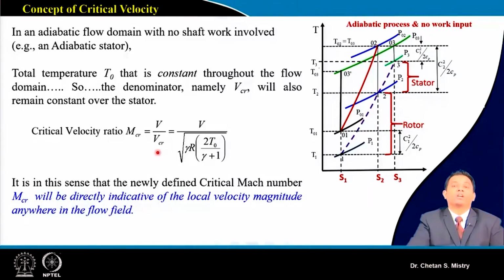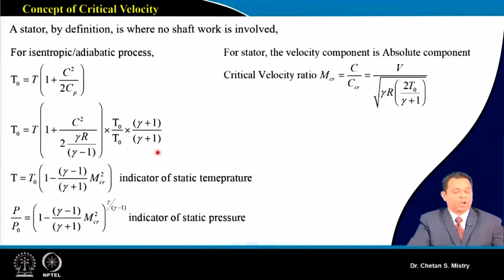Okay, for all configurations. People who are working in the area of gas turbines always calculate this Mach number based on the critical value, not based on the local temperature value. Now here, if we consider that we have our stator, and we want to calculate that part, we can say that for my stator, the process is assumed to be an adiabatic process.